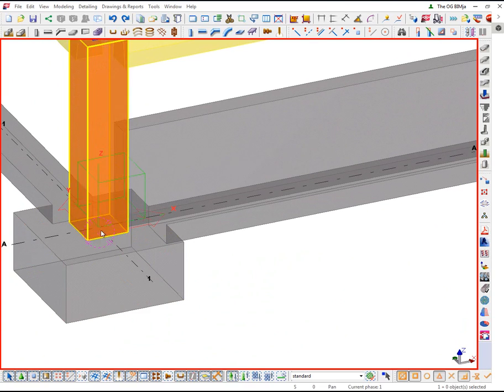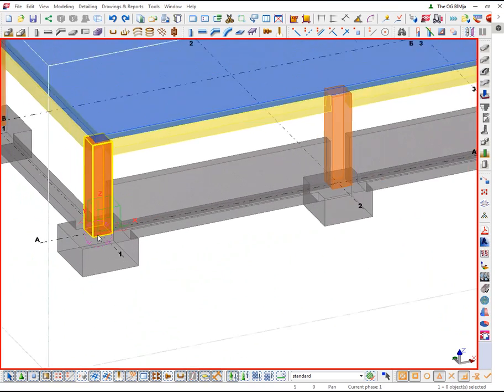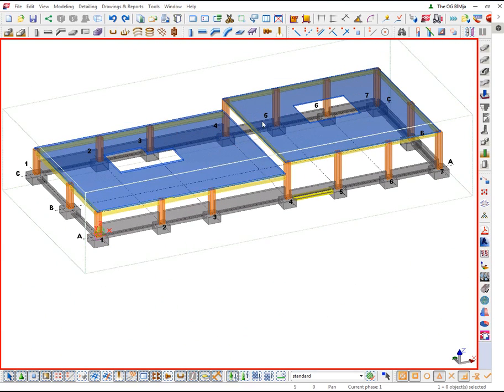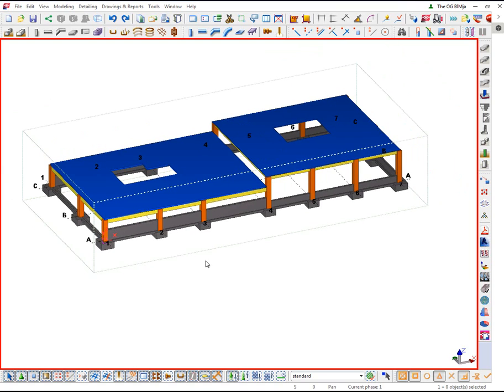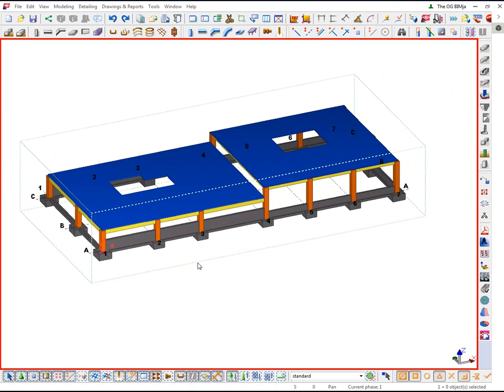So this little green cube right here, this point right here, is what Tekla is using to produce the IFC. So this is my origin. So you can see that I've modeled in my origin at 0, 0, 0. Now I know we're not all lucky enough to always work in a relatively small, close origin point. So this video is going to show you how to adjust the IFC files for you. So what I'm going to do is first I'm going to create a baseline IFC.